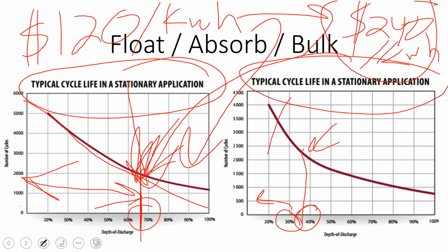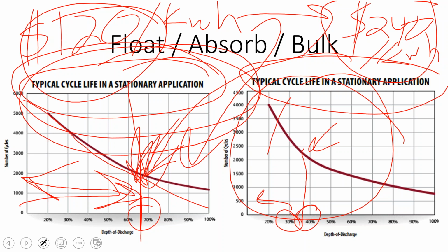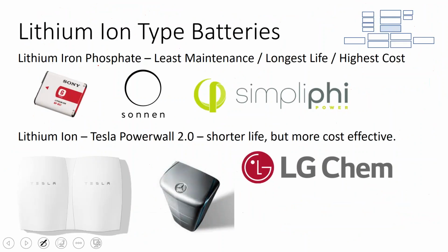Usually by going deeper, you're generally buying a heavier battery. And so these industrial forklift batteries become problematic when actually trying to move them around on site, whereas with the renewable energy battery, yes, you might need to buy twice as many of them, but they cost half as much. The big difference is now you have twice as many batteries to wire up, but they're more transportable. Versus using an industrial forklift battery, you might have a lot of problems during the install moving the batteries on site, but once they're landed, you only have a very small number of batteries to deal with. We'll look at some pictures when we get into the case study.